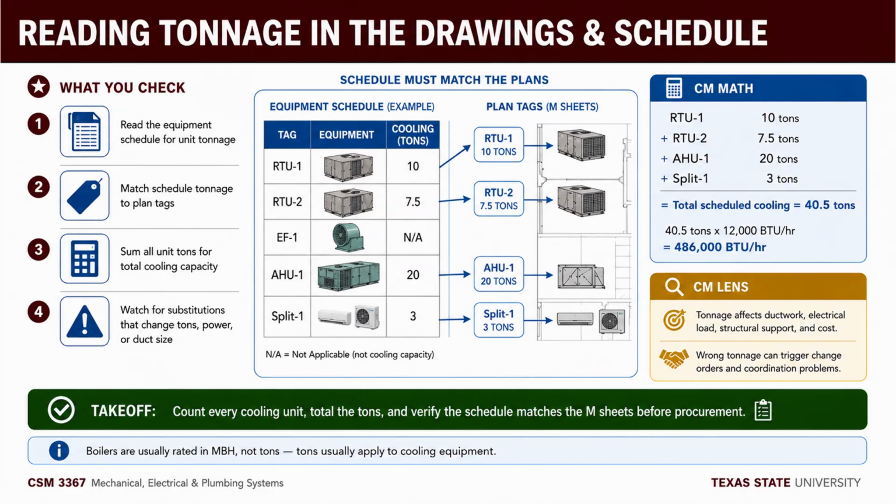Quiz alert. West-facing glass is the worst for summer cooling: low afternoon sun angle, unshadable by overhangs, and it coincides with peak outdoor temperature. South glass is high angle in summer and easy to shade with overhangs. Building peak cooling load typically hits mid to late afternoon.